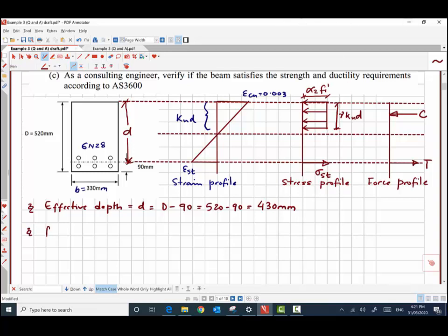And for compressive strength of concrete as 32 megapascal, we know that alpha 2 you can find out using the equations that we know is 0.8, and gamma using the same equation like before, it is 0.89. This is from AS3600 8.1.3.